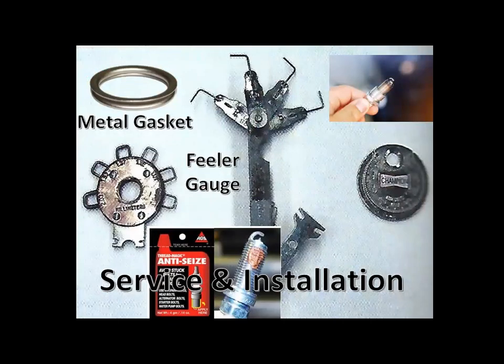When installing a new set of spark plugs, always use the spark plugs with numbers specified by the vehicle manufacturer. Spark plug electrode gaps must be set to the vehicle manufacturer's specifications using a round wire feeler gauge or a gapping tool. If spark plugs require a metal gasket, always be sure this gasket is in place before installing the plugs.